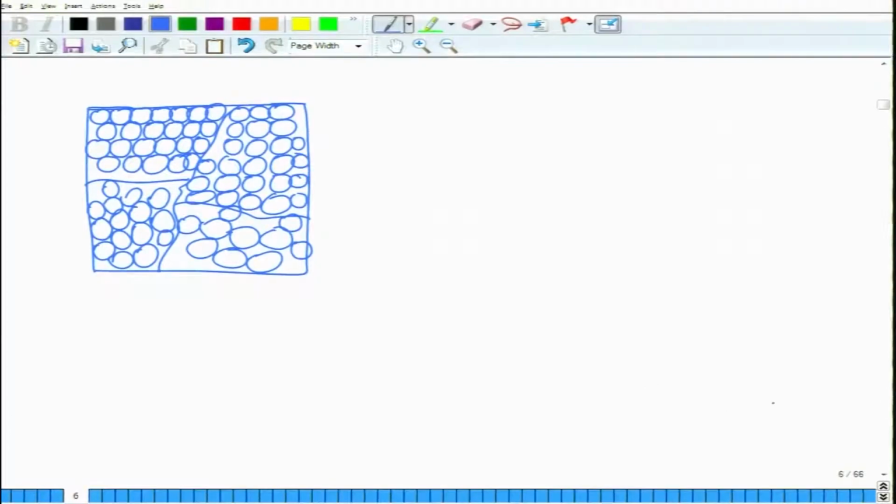So, you can see that if you take a particular vector, let us say this is the close pack direction in this case, this close pack direction lies in this direction, in this region it lies in this direction, in this region it lies in this direction, in this case it may lie in this direction. So, as a result they create boundaries between them, which are the regions of misorientation, where the orientations do not match.